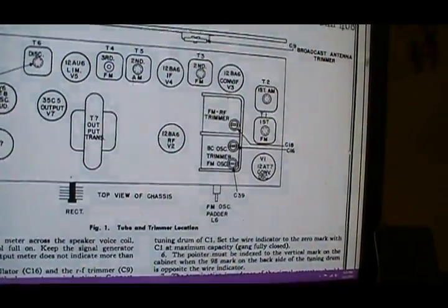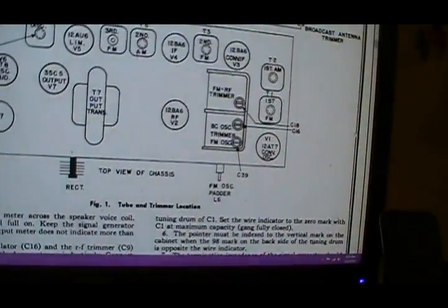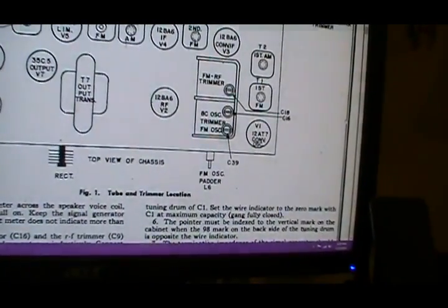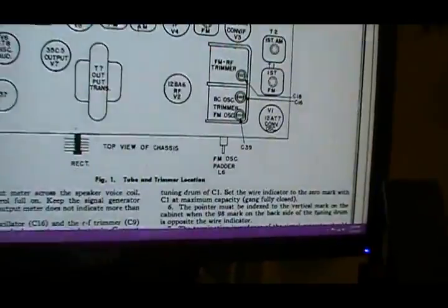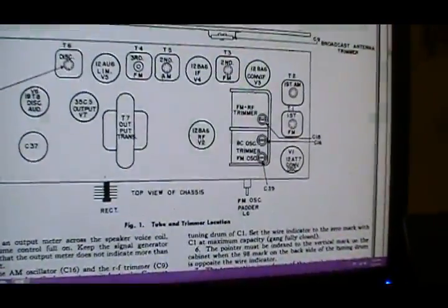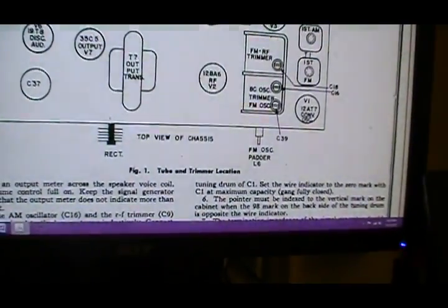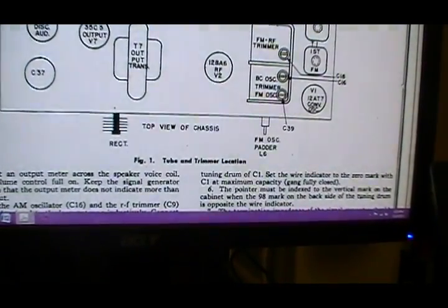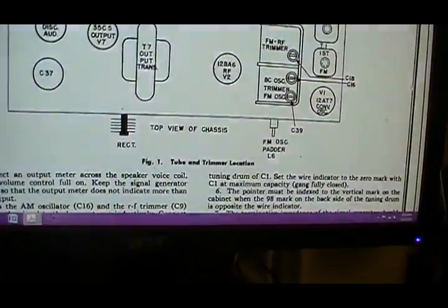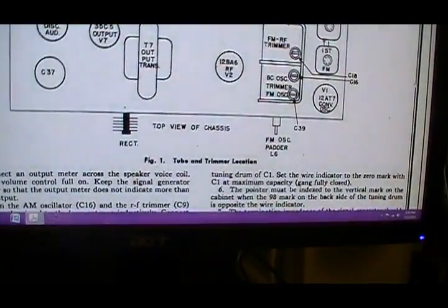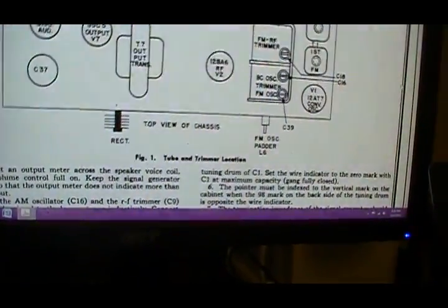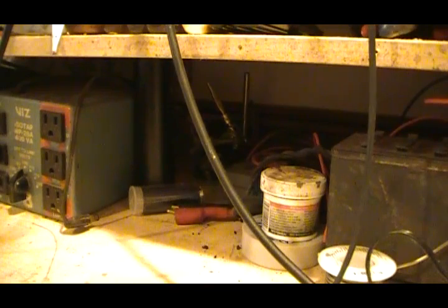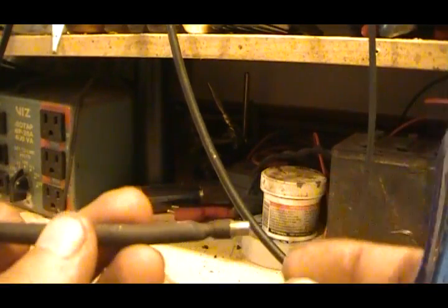But on it, when you get to doing the oscillator and doing those adjustments, you actually will be required to bend the coils if it's out of whack, if it needs adjusting. So you either squeeze them in a little bit or stretch them out a little bit, and their instructions basically state that you use a little tool like this.